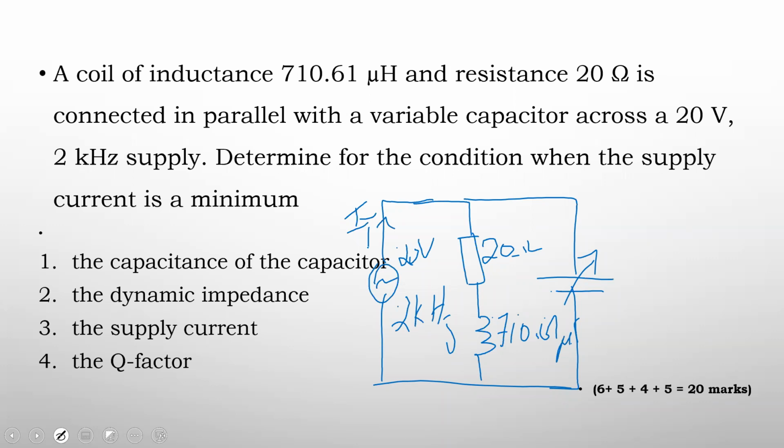Yes, sir. So based on the previous information you gave us, omega r is equal to 1 over the square root of 1 over LC minus R squared over L squared, right? So of the frequency at resonance, we could transpose for that to find C from the equation, basically. Okay, which is what I was asking, because there's no need for you to find the impedance of that branch. It doesn't advance the question in any way.